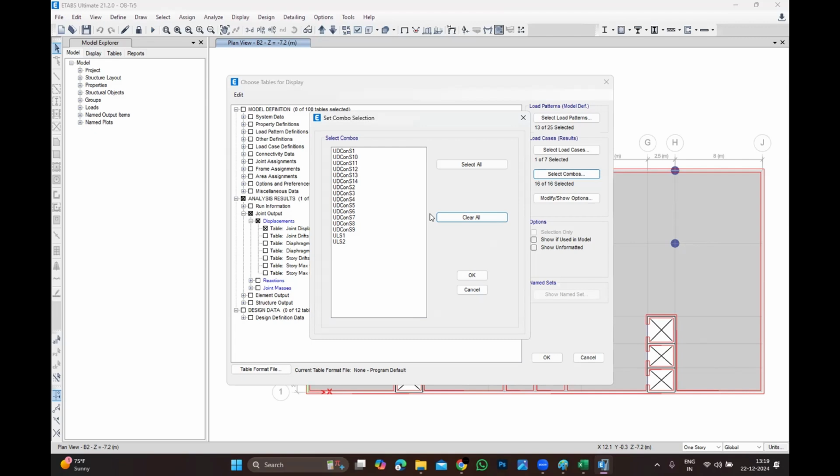Then the seismic will not dominate, the wind will dominate. If you are talking about 30, 35, 40 stories, seismic will dominate. But if you are talking about more than that, 70, 80, 85, then, but even the shape of the structure also matters. The shape of the structure is like a square, a rectangle. Again, my reference, I will change the number. But if it is slender, then the wind will dominate. But you cannot say, you have to check both.